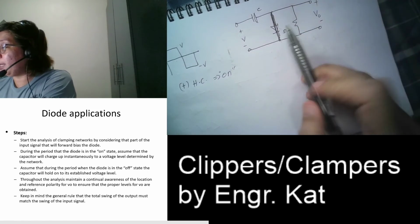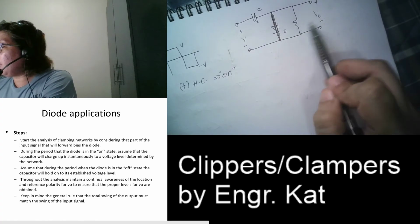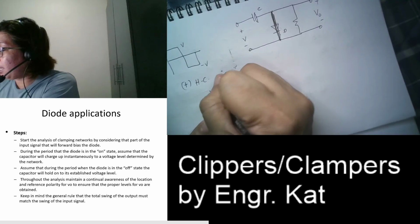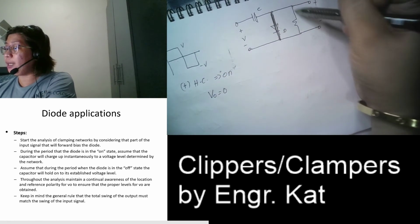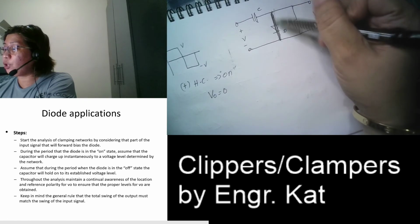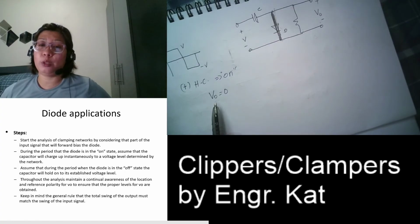Since this is shorted and in parallel with your resistor, and that is in parallel with your VO, we can say that your VO is equal to 0, because this is shorted and this is in parallel. So the voltage across this is equal to 0. Therefore, your VO here is equal to 0.